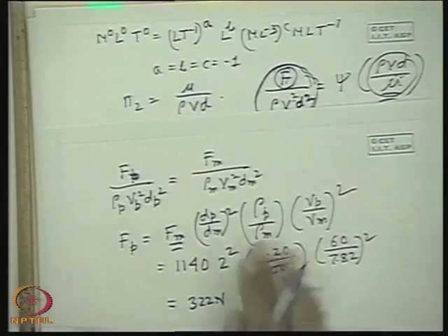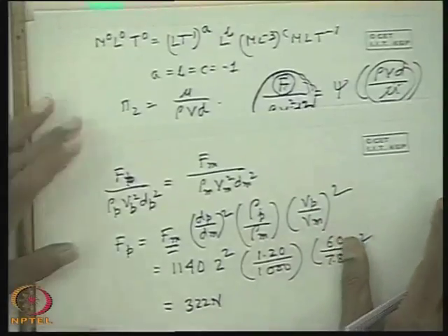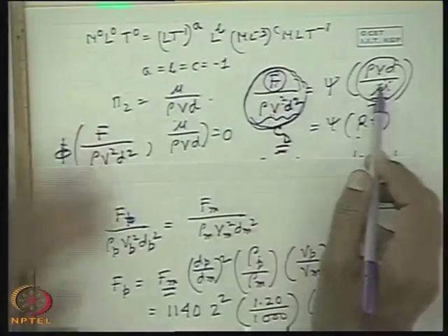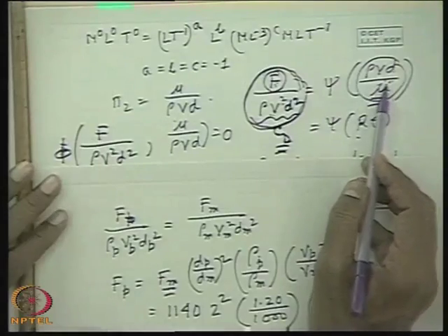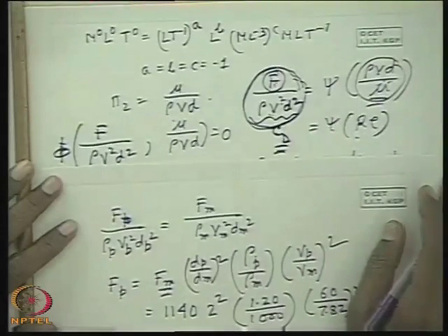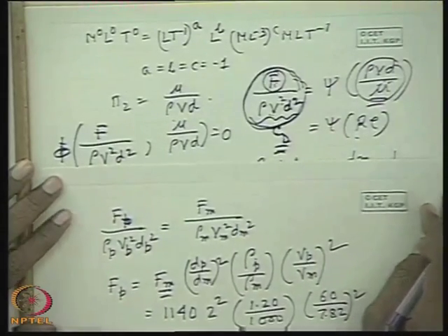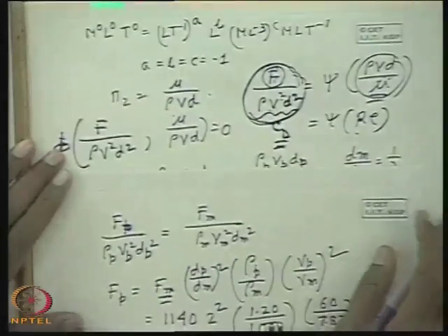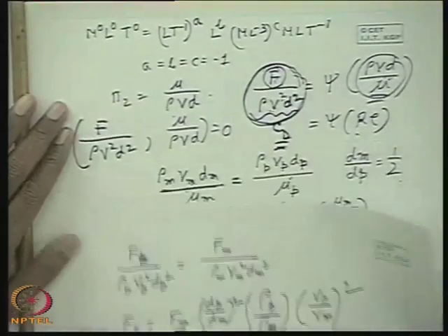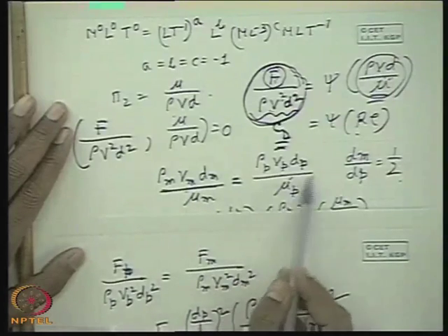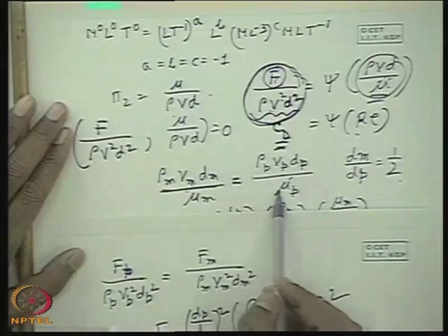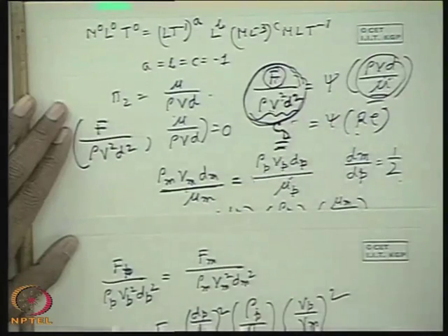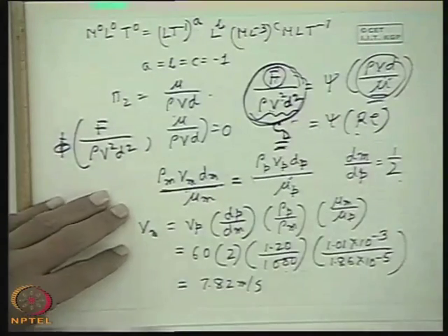Now you see this problem explains two things very beautifully. First of all, how to obtain the similarity or dimensionless parameters by the use of Buckingham's Pi-Theorem for a particular physical problem. Then how to apply these non-dimensional terms for these problems between laboratory tests and the actual practice, where the problem is same, problem physics is same, but they are under altered conditions.